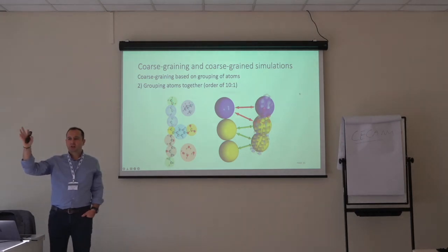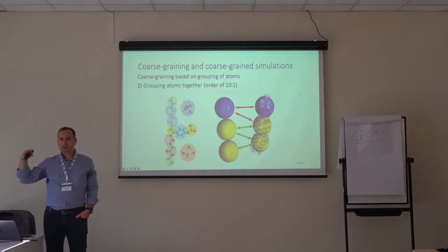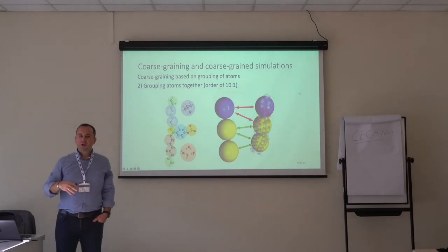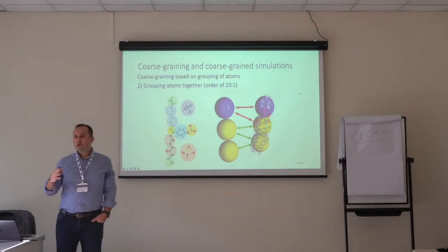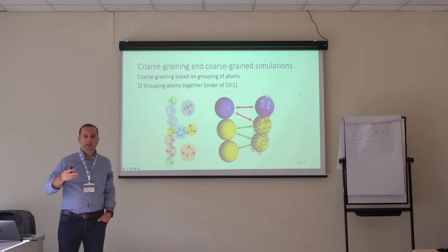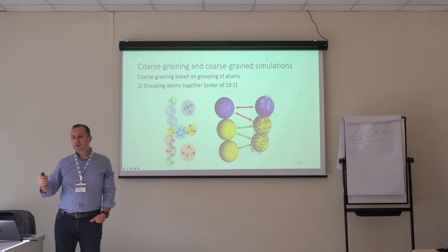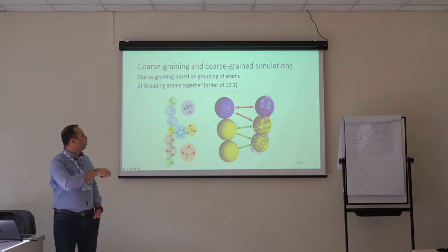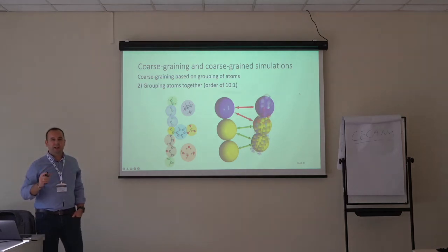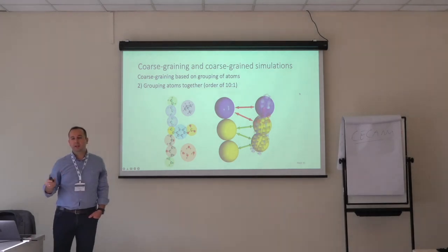structures governed by certain force fields which are available in the literature, in the programs, etc. But in the coarse grain simulations, that is different. You don't really have a set of force fields, especially for DPD. You need to compute by yourself. So you need to consider what kind of coarse graining you have, which coarse grain bead represents which molecule, etc., and you compute the interactions between these superatoms, or we call them beads, by yourself. That is the trickiest step of coarse graining if you are doing DPD.